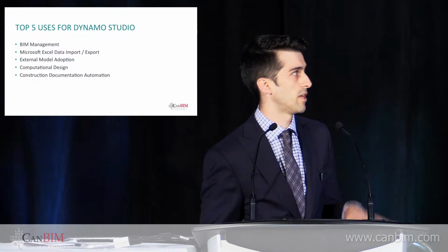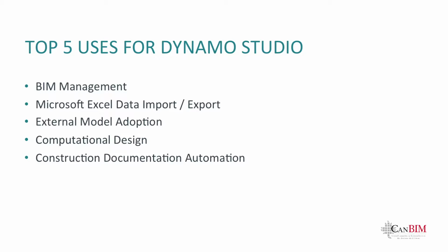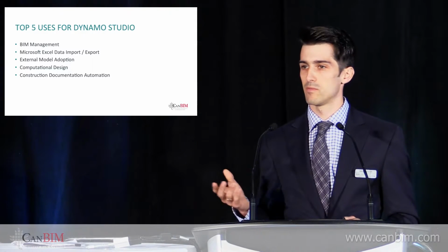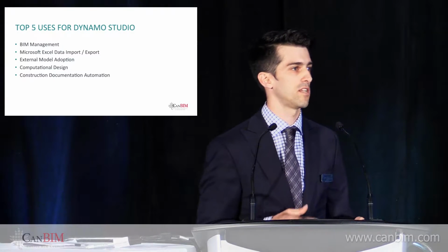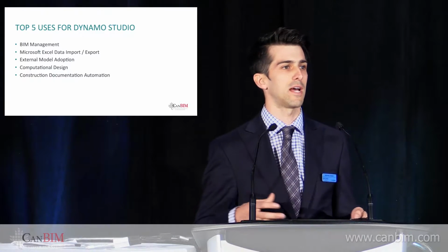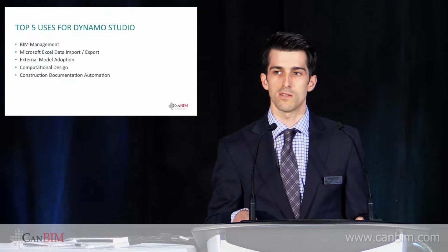Top 5 uses for Dynamo Studio. BIM management, so you can use it to alter mass amounts of text or parameters. You can use it to alter certain things like door heights globally throughout your project, or code-related items, like certain things that you can manage in your project, like stripping views, renaming certain sheets. All these things that take a lot of time don't need to take time anymore.